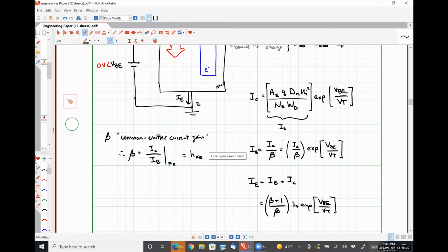So what I want to talk about at the very beginning of Monday's class is introducing a second transistor parameter. It's kind of the complement of beta, which is called alpha, the common base current gain, and then how it relates to these equations, and then we'll move along from there. So we've effectively well described, at least in my opinion, you may disagree, the operation of a BJT in the forward active region and all of the different mechanisms for why currents are flowing in the directions that they do and all that kind of good stuff.